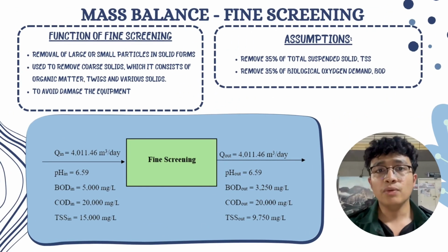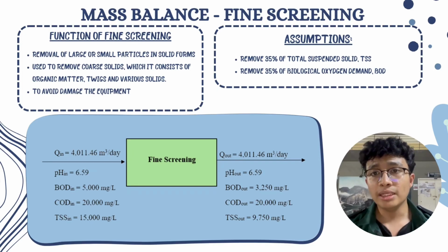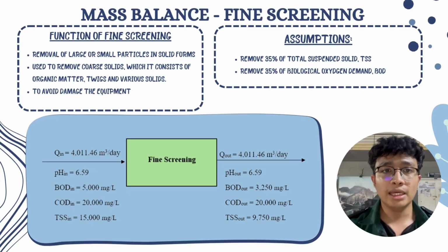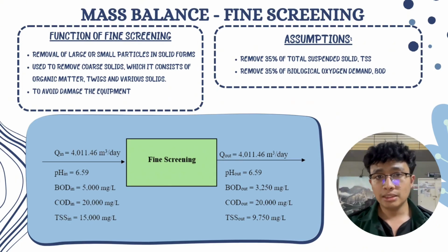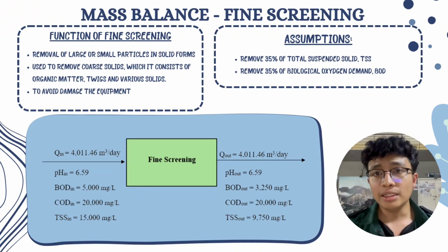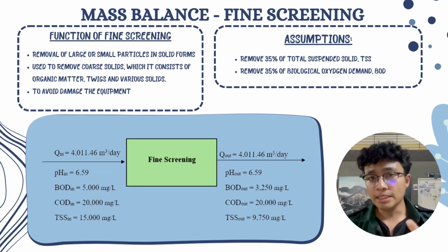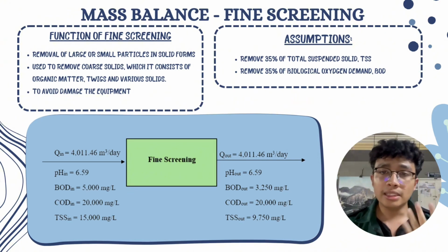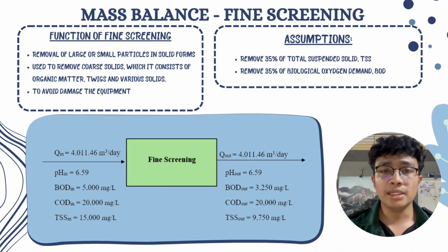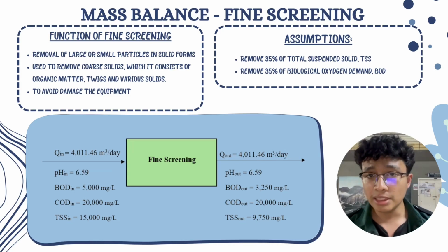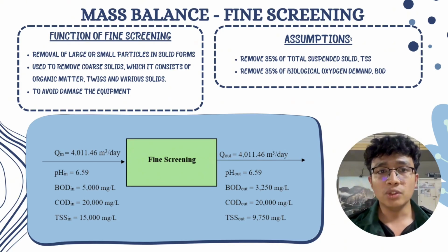The industrial effluent treatment system is used to treat wastewater from industrial activities before it is discharged into the environment. The treatment process follows several stages: preliminary, primary, secondary, and tertiary treatment. This ensures that the wastewater meets the Industrial Effluent Regulation 2009 before being released into water bodies.